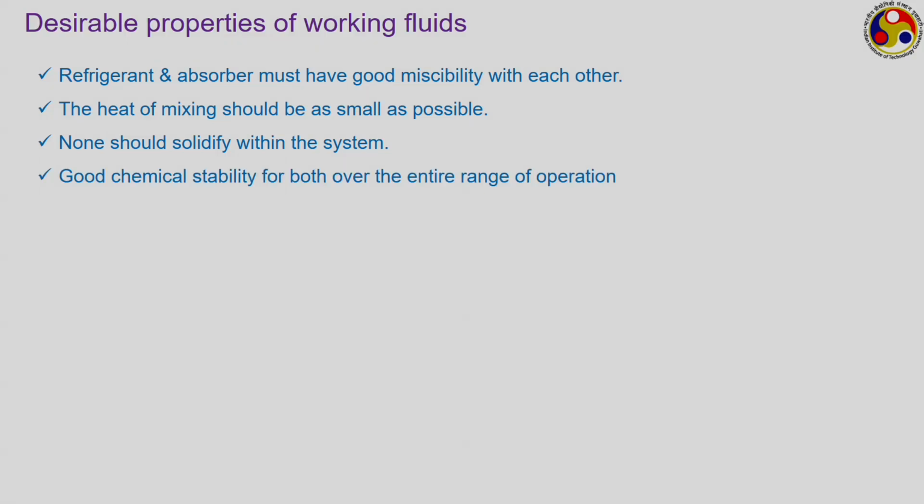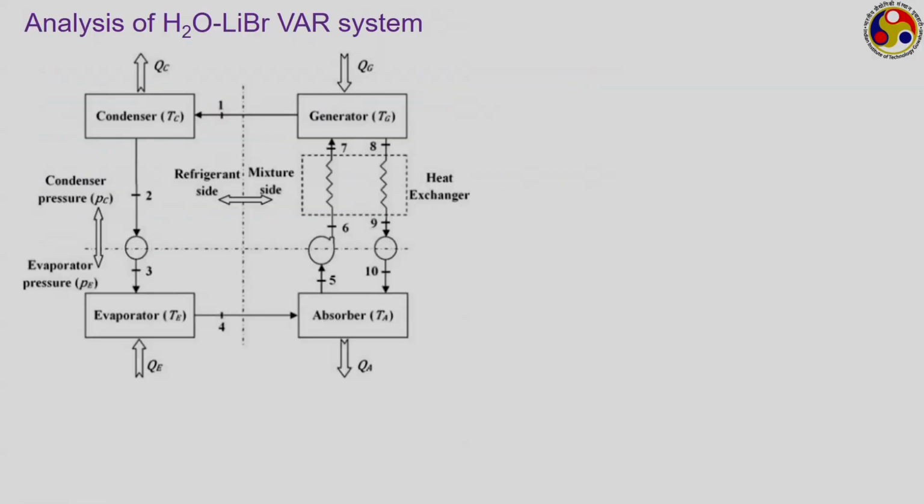They should have good chemical stability over the entire range of operation. Viscosity should be low, so that there are very small frictional losses and the pump work input requirement is less. Also, the thermal conductivity should be high to have good heat transfer characteristics, and they should be non corrosive to the metals that are being used.